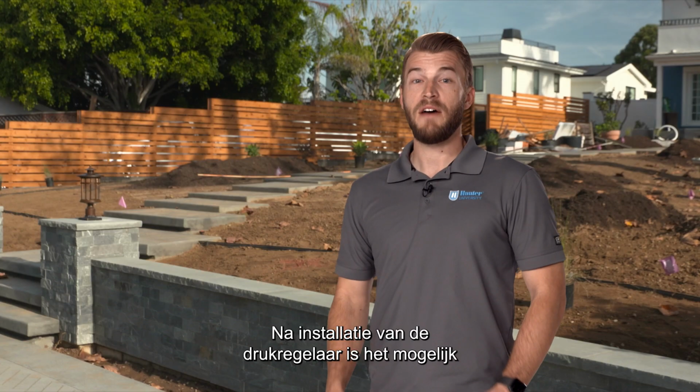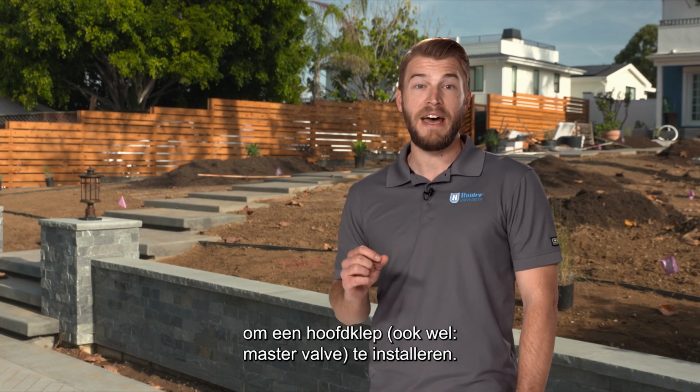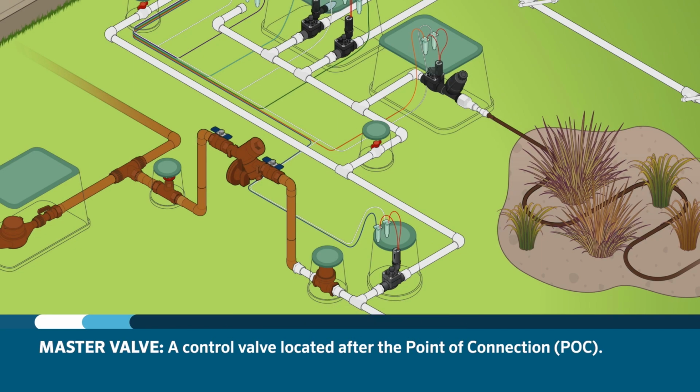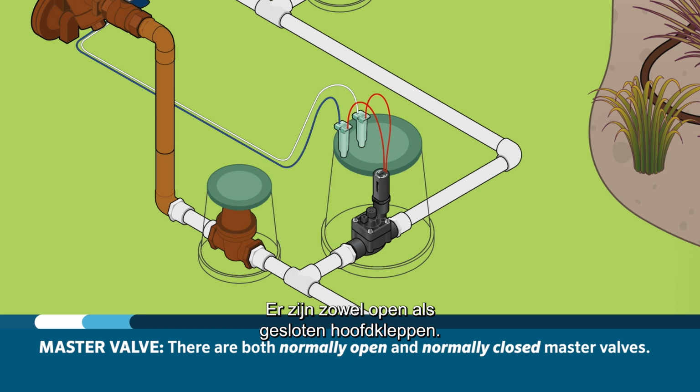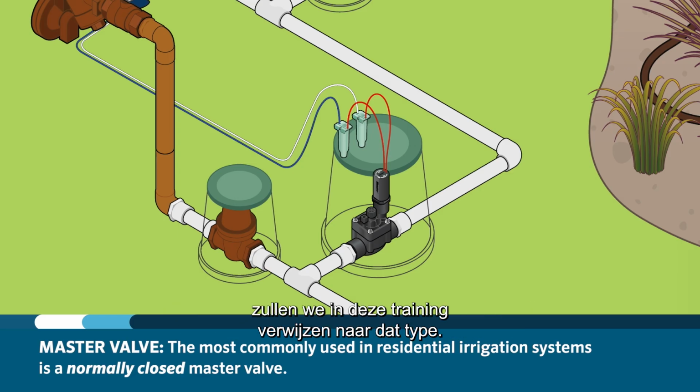After the pressure regulator, an optional and highly recommended device known as a master valve can be installed. The master valve, in most cases, is simply a control valve located after the POC. There are both normally open and normally closed master valves. Since a normally closed master valve is the one most commonly used in smaller irrigation systems, we will be referring to that type during this training.